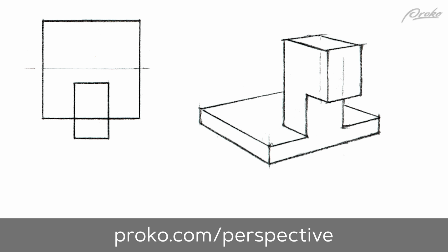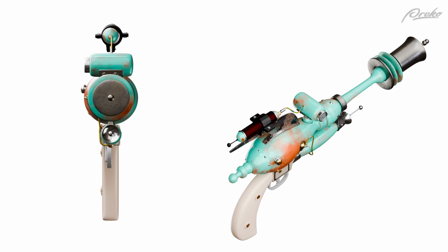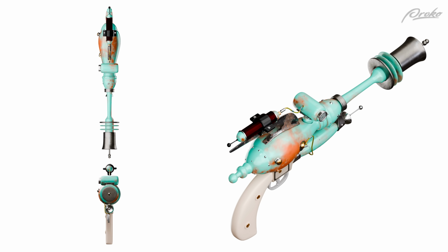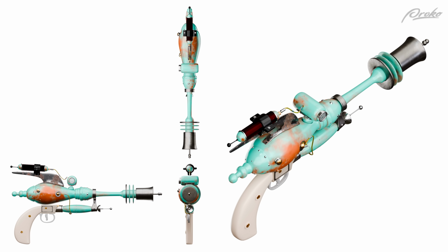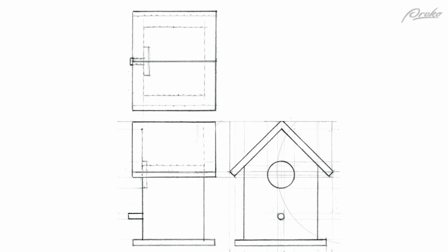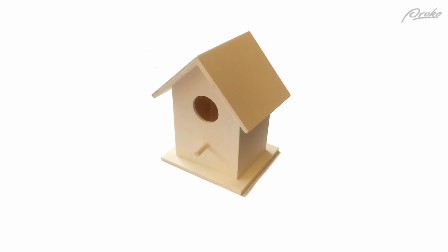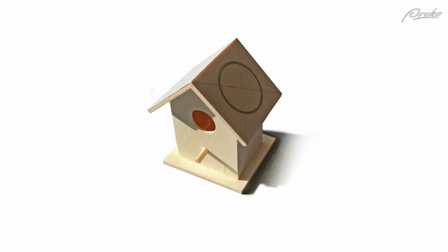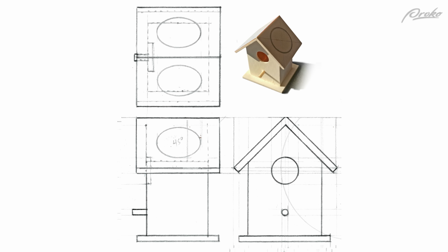But let's review the laws. Every front and top view will line up on the widths. Every front and side view will line up on the heights. Ortho law. Remember why this came about. This simplifies going from paper to space, drawings to objects. But we're going to work in the opposite direction, space to paper.